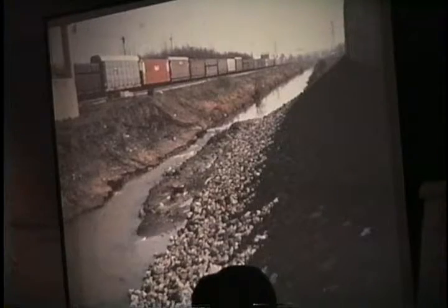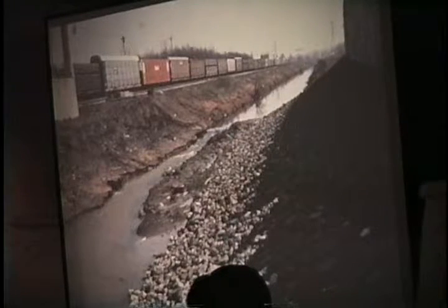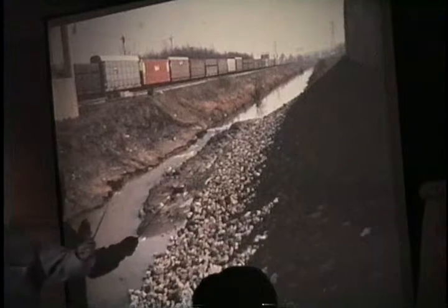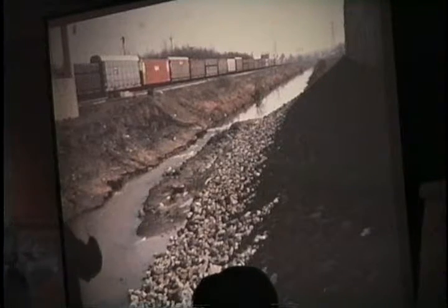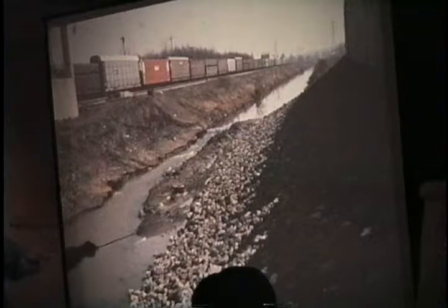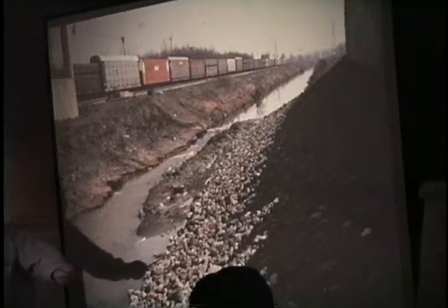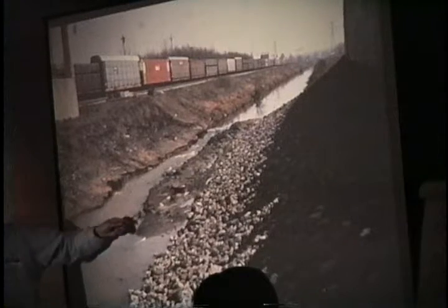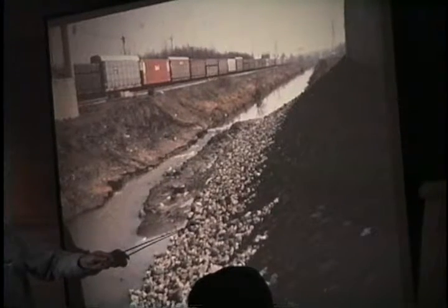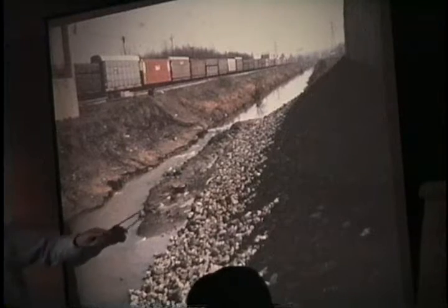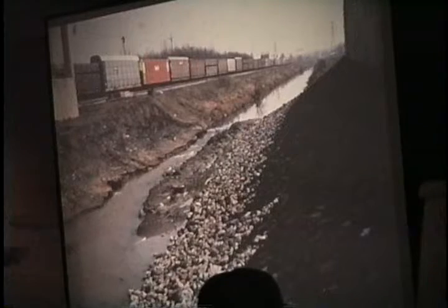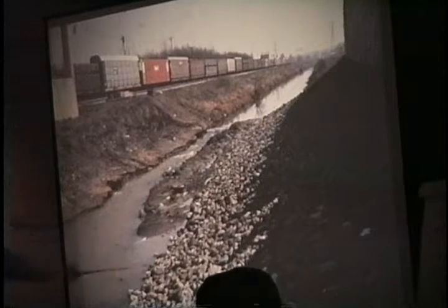So, bulging: this is the Louisville case. The embankment moved laterally. It slid on that weak, thin layer of clay, and as this embankment moved forward, it squished up all the weak material in front of it and below it, squeezing it out like toothpaste, because some of the highly plastic clay was mixed in there too.